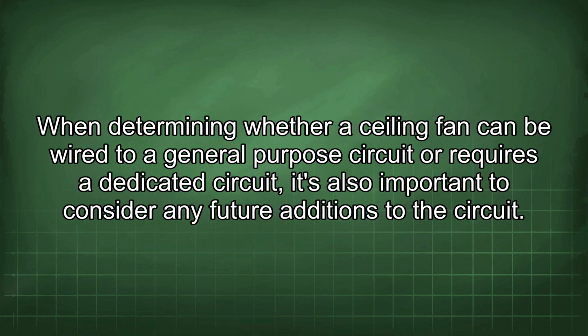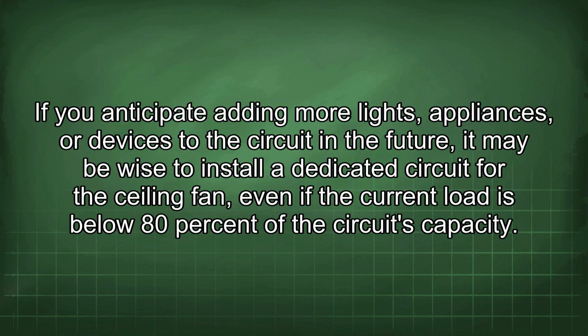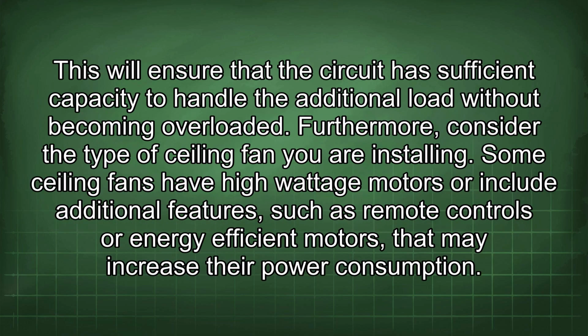When determining whether a ceiling fan can be wired to a general-purpose circuit or requires a dedicated circuit, it's also important to consider any future additions to the circuit. If you anticipate adding more lights, appliances, or devices to the circuit in the future, it may be wise to install a dedicated circuit for the ceiling fan, even if the current load is below 80% of the circuit's capacity. This will ensure that the circuit has sufficient capacity to handle the additional load without becoming overloaded.